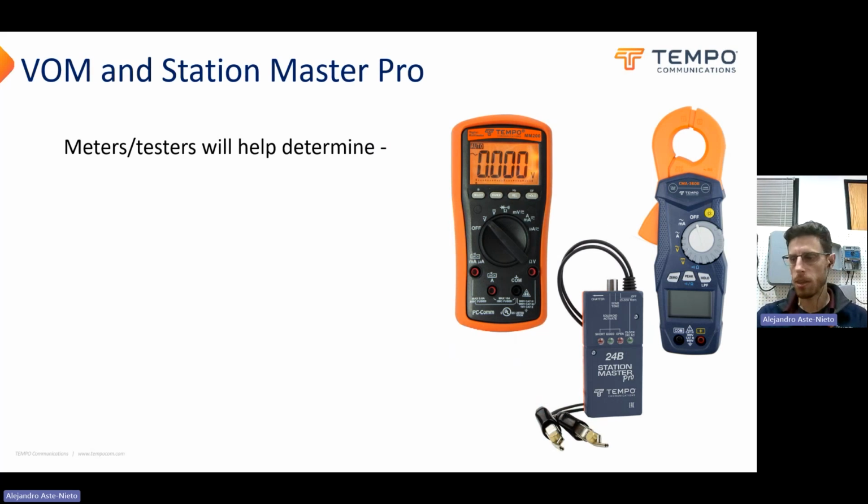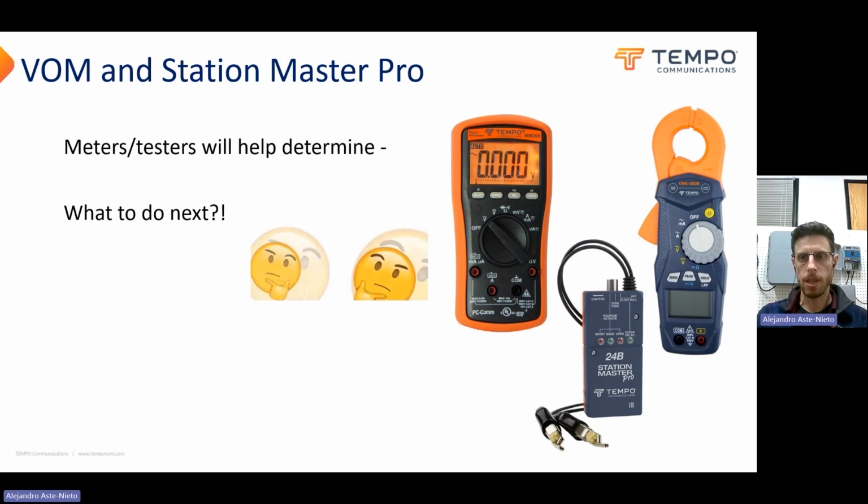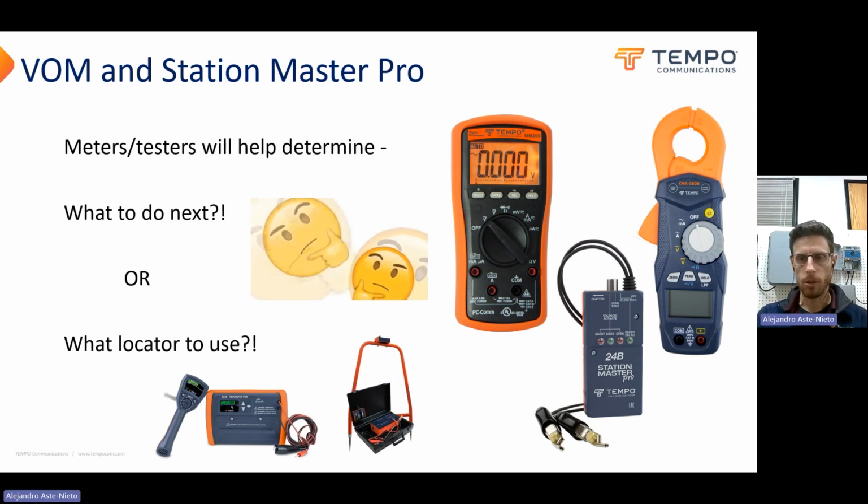So these are very useful tools to help you narrow down problems and understand what to do next, or if you really want to save time, to figure out what locator to use. You might know that the problem is somewhere between controller and valve box in a wire, and a locator is going to be very helpful in narrowing down where that problem is located.